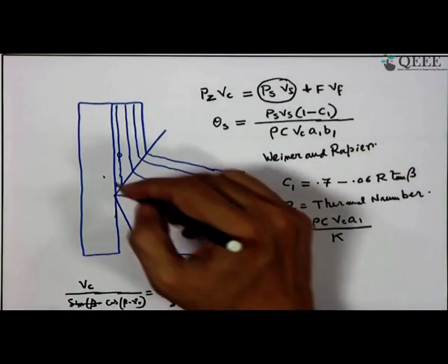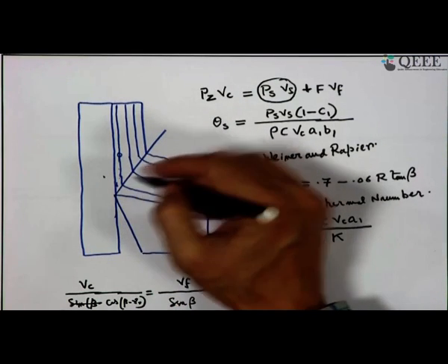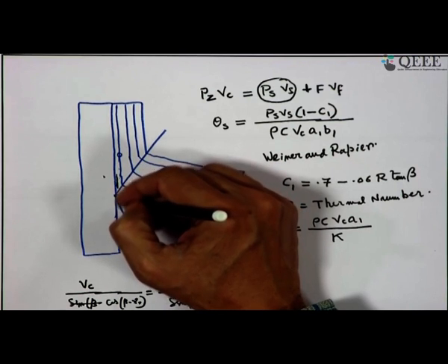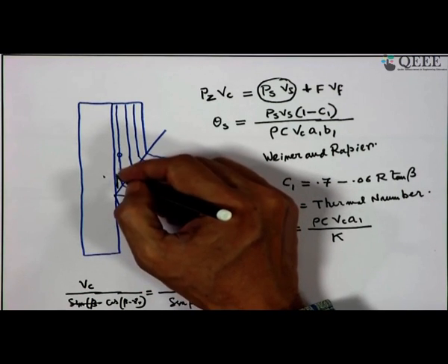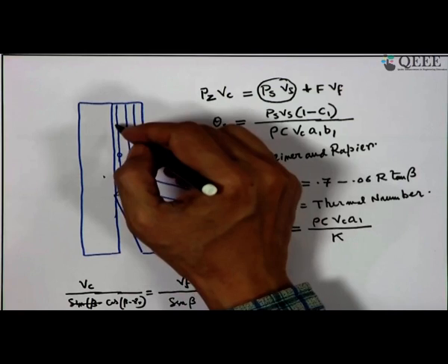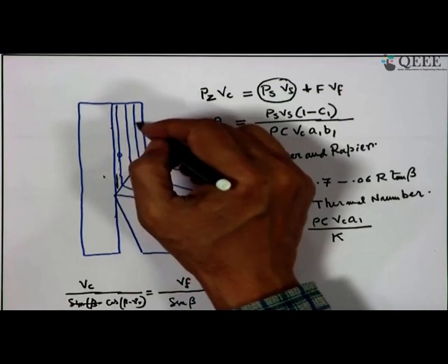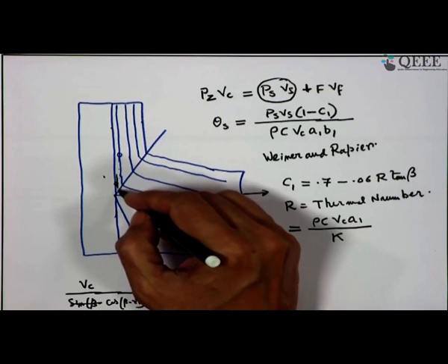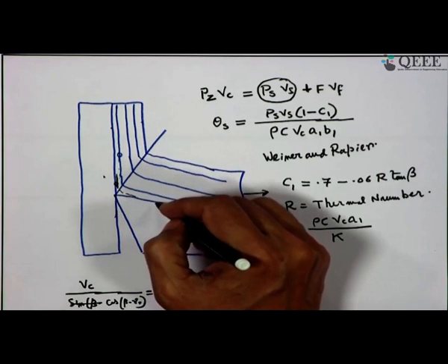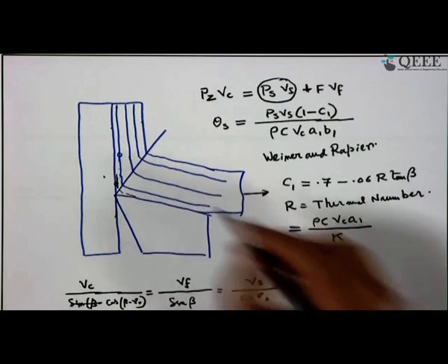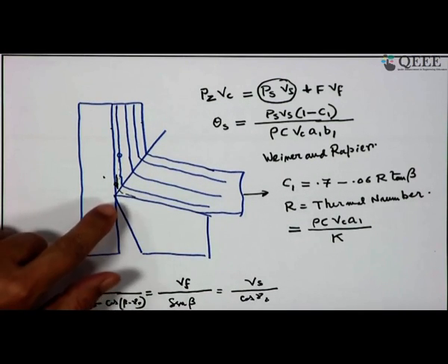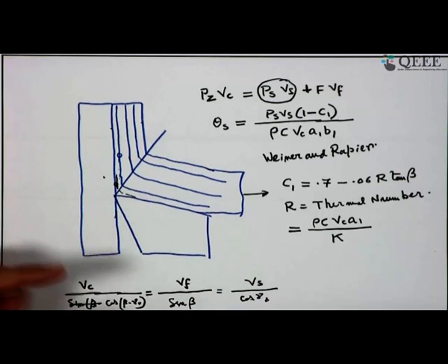However, as it moves, all the points very close to this line, that means from the free surface to this depth level of the uncut layer, a point situated in this level will almost come in contact and be located at the chip tool interface, and as a result, it will attain a further rise of temperature.